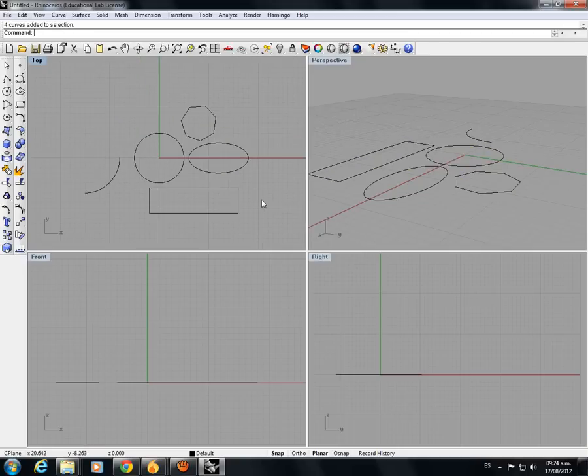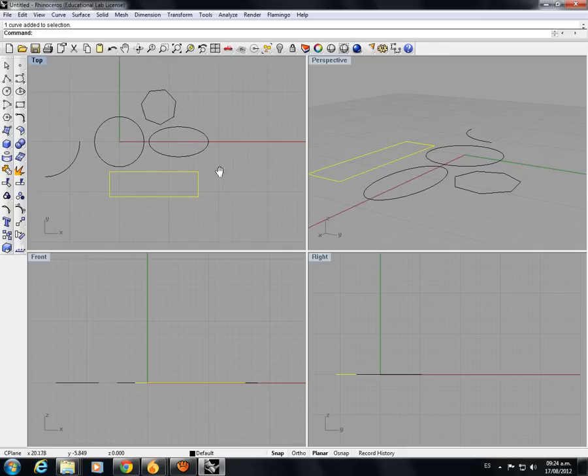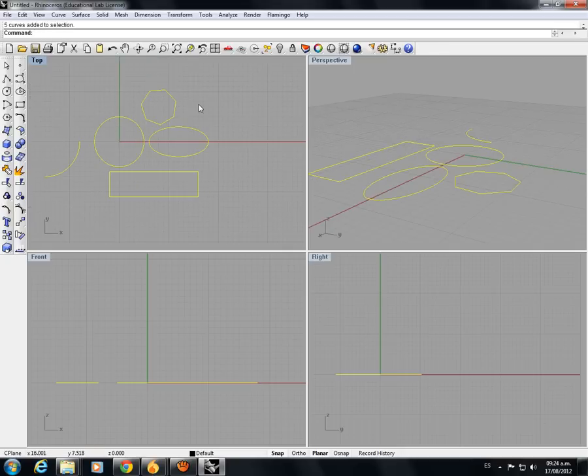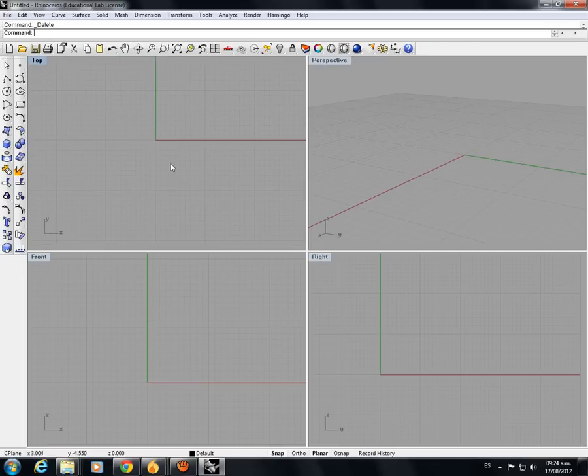Okay, now after we finish this, you can erase again your shapes. It's important that you do this exercise, even though we're erasing them at the end, because it's a practice tutorial. Okay, so now I'm gonna jump into creating solids. Now when I create solids, I can click and hold on the box, and the first one that I'm gonna do is a box.